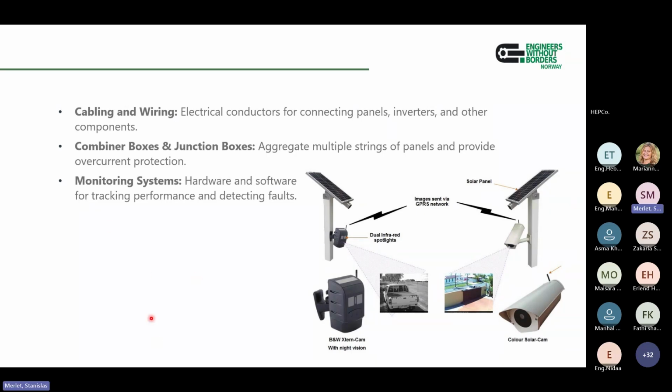Yeah, so you would measure wind, irradiation, temperature, both ambient temperature and the module temperature, as mentioned by Michel on Monday, and put all that in a huge data log to ensure good operations and performance of the PV plants. But the monitoring also usually includes safety of the plant. So that could be cameras, could be also some kind of sensors on the fence if needed, and all of that. So that's just monitoring the whole plant.